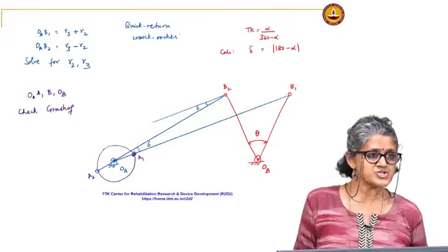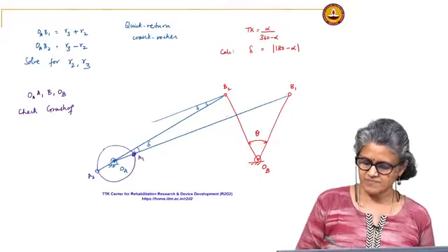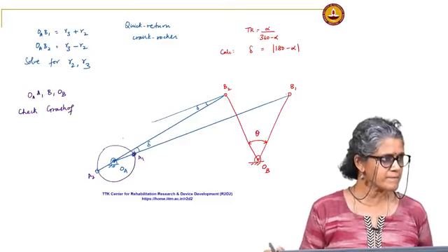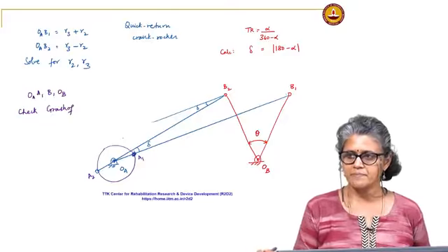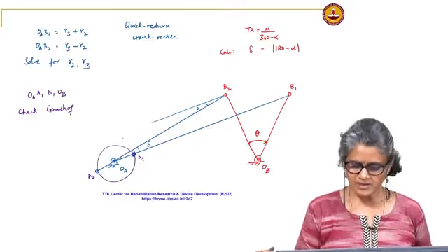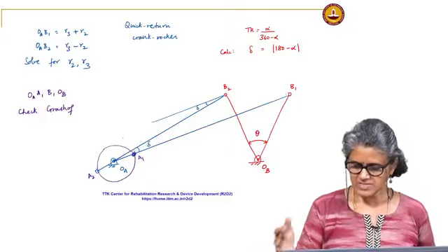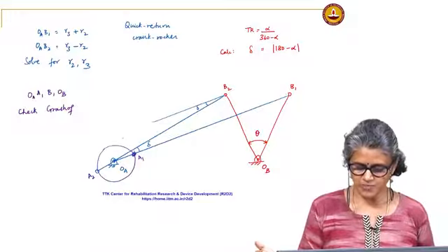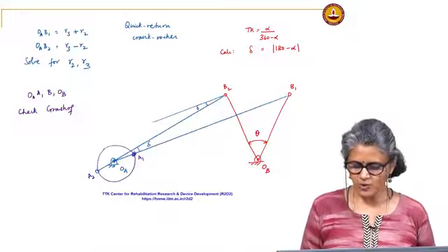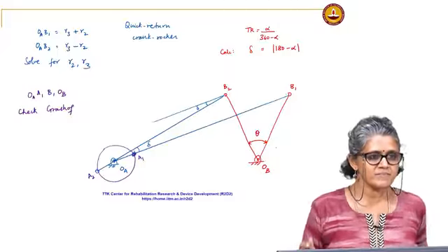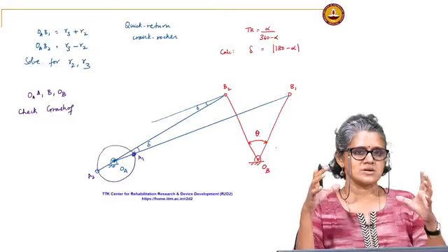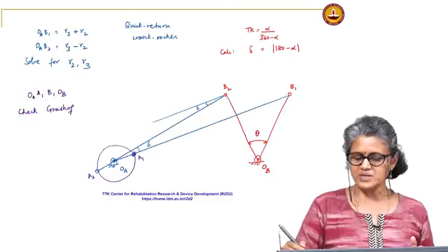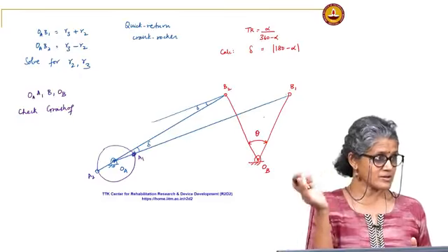Again, I made a lot of free choices. For instance, this line that I drew through B1, I just took it at random. I made a free choice there. Next we will look at how I can actually have a certain offset. In this case, if I wanted a certain orientation of OA and OB, I would just design my linkage, then reorient it, provided I had flexibility in reorienting the rocker output.